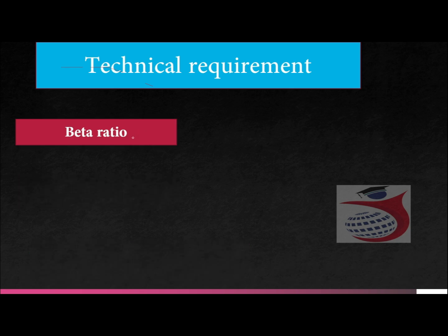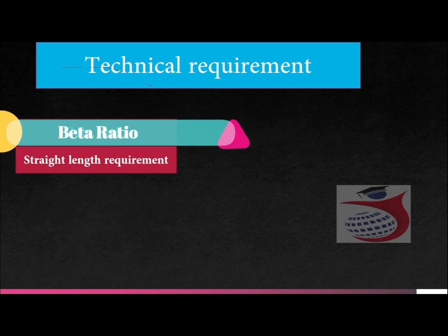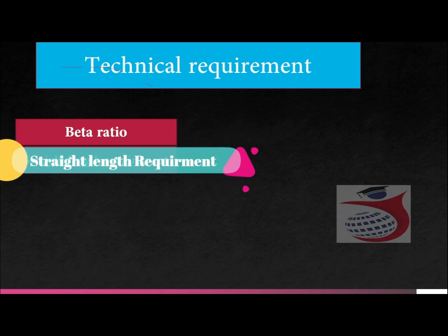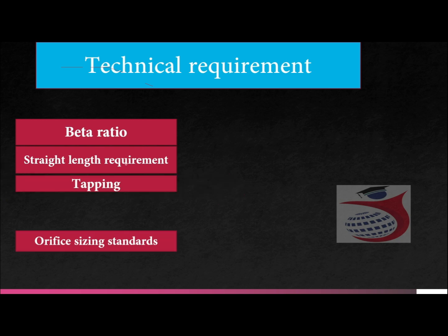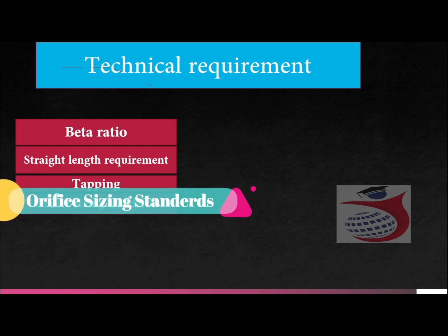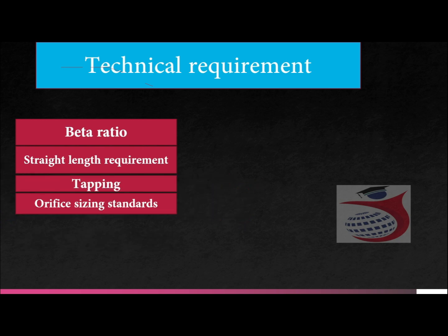What are the technical requirements? First one is the beta ratio. Second one is straight length requirement. Then we will learn the tapping. Then we will learn the orifice sizing standard. What are the standards we follow for the orifice sizing?